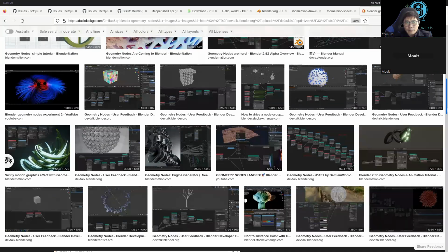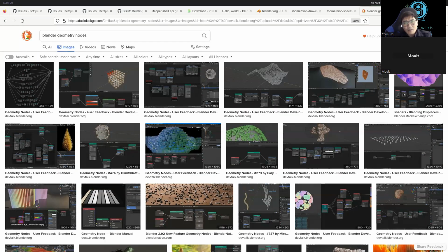Yeah, you are right. Basically, when you extract it as an IFC model, it's actually a textual file, unless we want to see it visually in the 3D environment. If you export an IFC model using Python scripting, it just gives you a bunch of text in Notepad, for example. But if you change the Notepad extension to IFC, immediately it becomes a model that can be visualized in the authoring software.